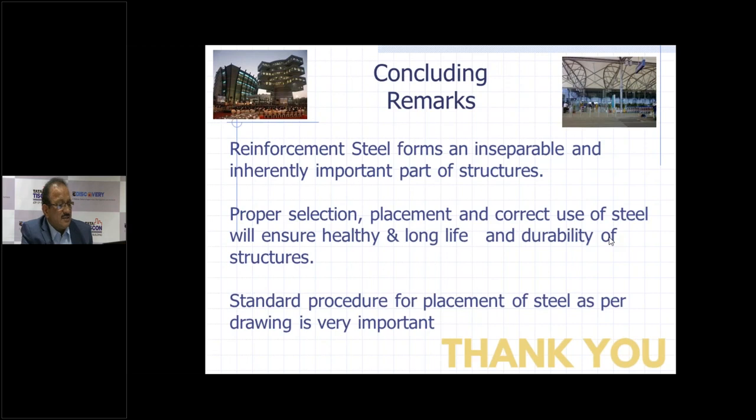Then you showed column reinforcement joining with couplers. Then what about lap length 40D? No, you don't have to worry about the lap length. It is a perfect joint wherein you don't have to worry about the lap length. We are avoiding the laps, and it has been proven beyond doubt that these couplers transfer the load, in fact, in a much better way when compared to the laps which we provide. So nothing to worry on that front.